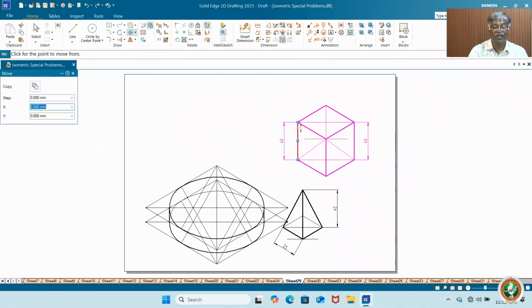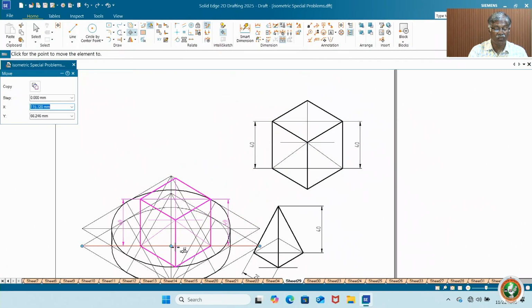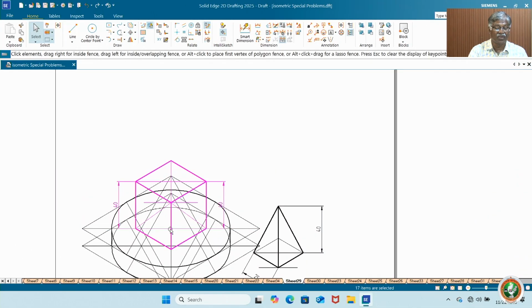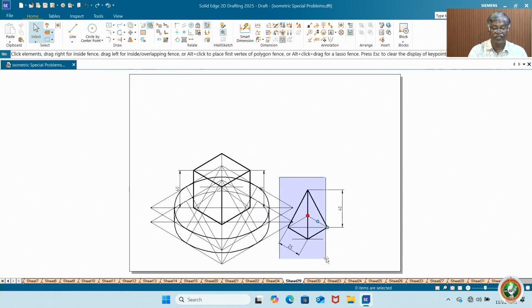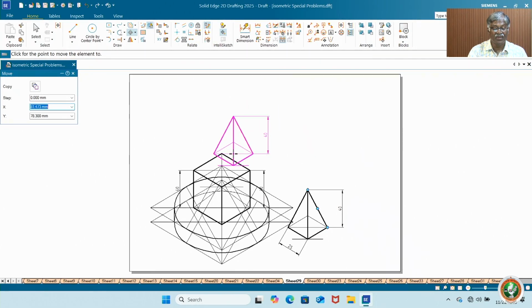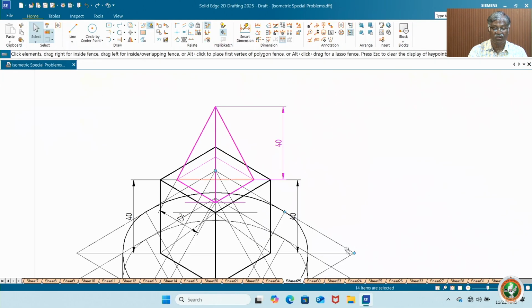Yeah, this one is light. Then keep this. Sometimes this may vary. Okay, now the base center of the top solid must coincide with the top center of the base solid. Now you can clear the visibility now itself, otherwise at the end you can do it. Next point is having this one at the top. So simply catch the center of the base here, that must coincide with the top center of the second solid. See, that's all.